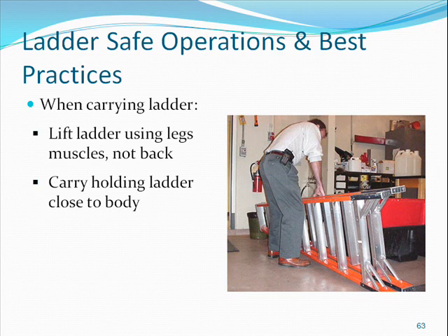You should carry a straight or extension ladder parallel to the ground. Hold the side rail in the middle of the ladder so you can balance it. Be aware that the ladder itself may be hazardous to others and proceed with caution. Of course, many ladders are long and heavy, requiring two people to carry them safely. When carrying a step ladder, make sure it's fully closed and it should always be carried by the side rail in the middle of the ladder.